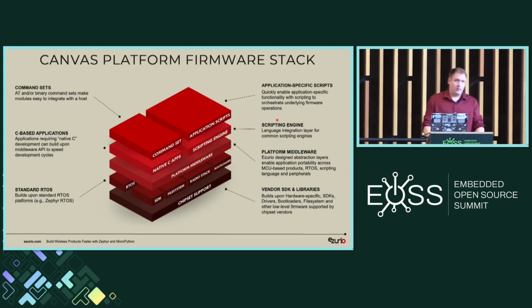And the reason this is important is in case we do have a product that doesn't support Zephyr, which we unfortunately do with a couple of our modules because they're based on a silicon that's not fully supported in Zephyr yet. So that's where developing those extra layers benefits us, so we can still build MicroPython for them and have it work the same way.